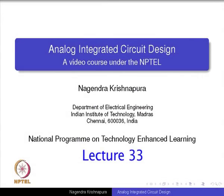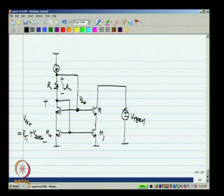So, if I connect it up like that, I can have my cascode biasing without using an extra branch. Previously, I used an extra branch to generate VG0, so this is better. Now, the disadvantage of course is that the drop between these two voltages is given by I naught R, and it relates to the absolute value of the resistance, and that is not very precisely fixed on an integrated circuit. Because of that, there is some uncertainty.